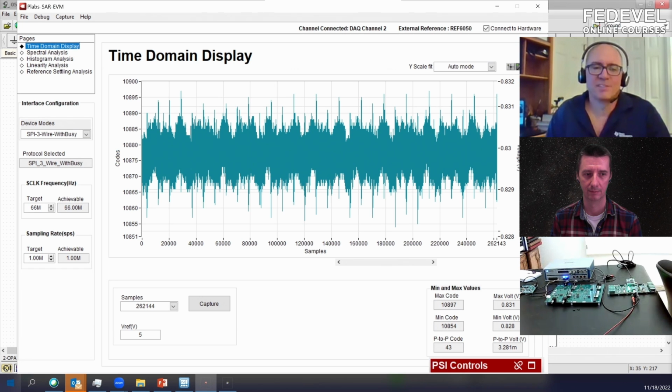Keep in mind that the resolutions that we're looking at here are quite small. So we're dealing with millivolts. In this case, often we're dealing with microvolts or even nanovolts that we're trying to measure. So we'll have 24-bit delta sigma converters that measure signals with least significant bits in the nanovolts, and so 60 hertz pickup could be quite problematic there.